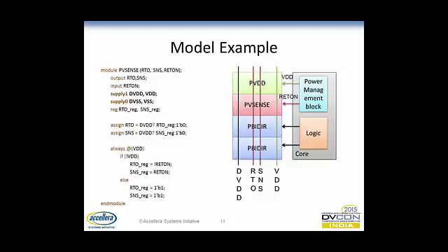The only thing is, if it is used normally, the supplies are tied internally, so it will just filter out the supply functionality and it will be a normal Verilog. But in a power-aware simulation, what the simulator will do is disconnect this supply 1 and supply 0 from within the model and tie them at the top level to the UPF supplies, and then this model can be directly used as a power-aware model without the supply ports being instantiated in the port list.